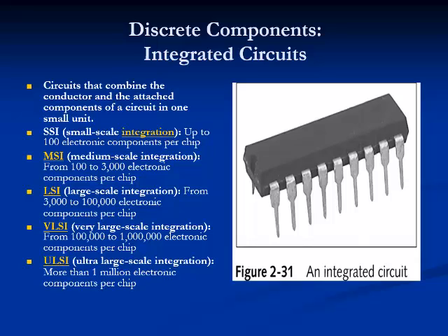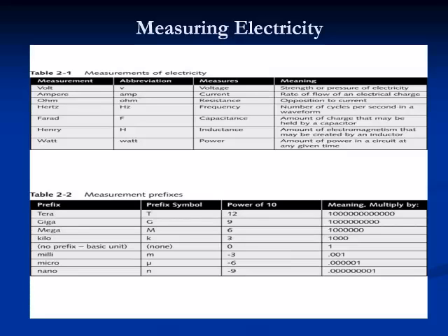A diode is an electronic component that acts like a one-way valve. As a discrete component or built into a chip, it is used in a variety of functions. Used as a rectifier, it is a key element in changing AC to DC by limiting current flow to a single direction. Diodes are used as temperature and light sensors and light-emitting diodes. In communications, they filter out analog and digital signals from carriers and modulate signals onto carriers. In digital logic, they're used as one-way valves and as valves similar to transistors.